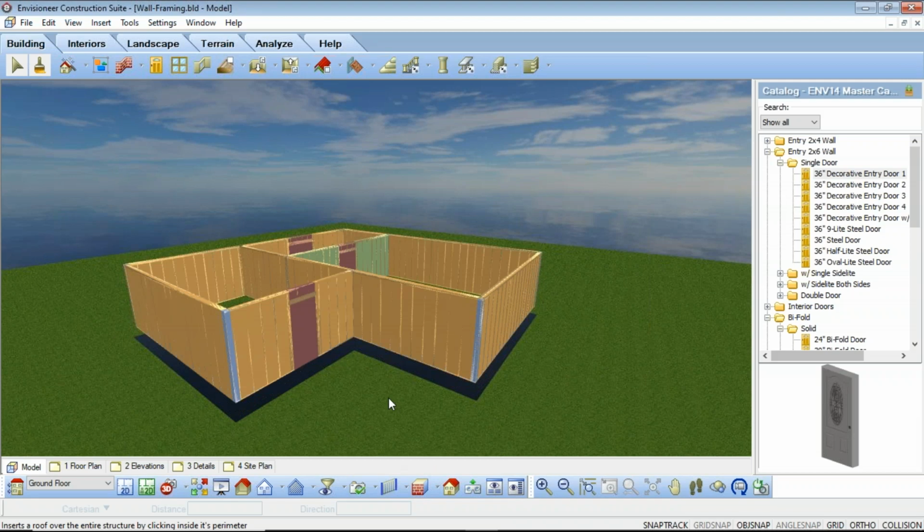So right now we're looking at our 3D model and we can see a bunch of different glass boxes. So orange, this is your wall infill for any load-bearing wall. As you can see, I've defined all my exterior walls to be load-bearing, and I specified this one interior wall to be load-bearing. I also have a green wall on my inside. That is denoting a wall infill that is a non-load-bearing wall. I see these red or wine-colored glass boxes. These are all of my openings, be it a window, a framed opening, or a door.